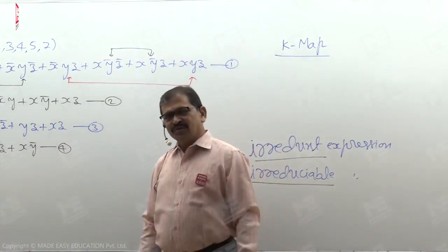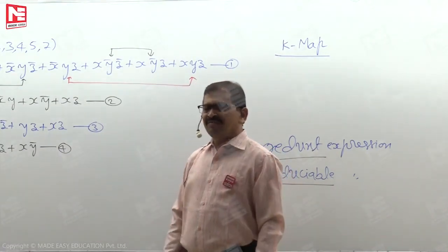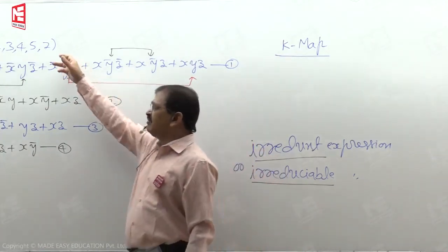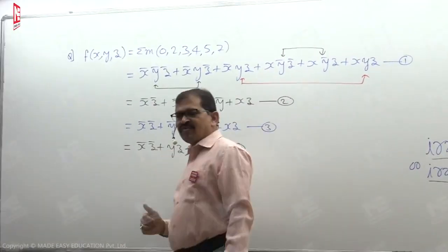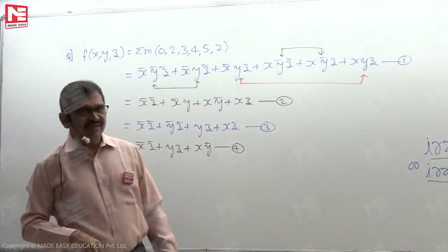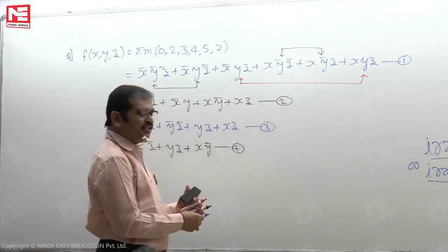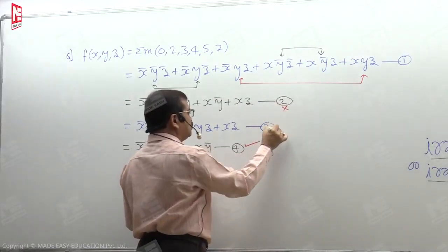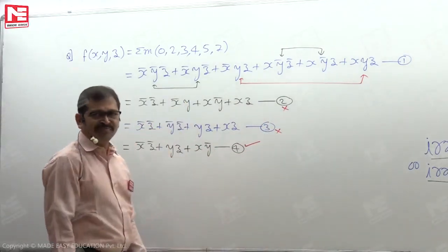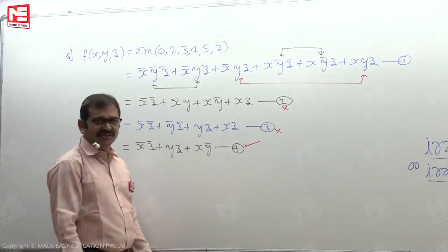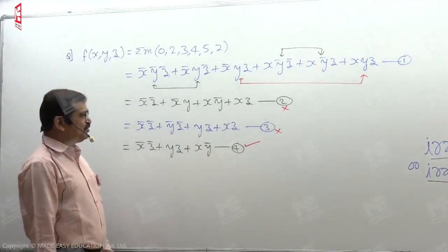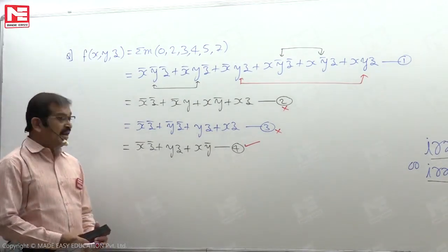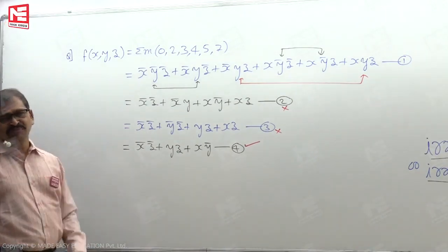So knowing this, if somebody is asking us to realize this function f, then based on the work we did till now, for realizing this logic circuit we prefer to use equation 4. We are not using equation 2 or equation 3. The reason is very simple. Equation 2 or equation 3 have 4 terms, whereas equation 4 has only 3 terms.